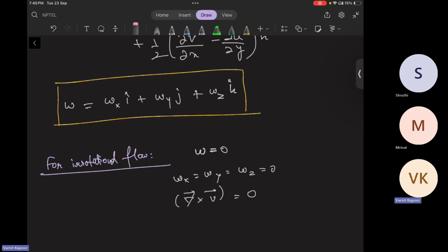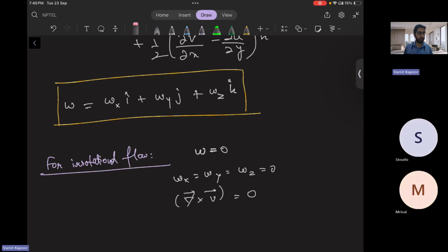All right. So let's come to the concept of circulation. Circulation is defined for the rotationality of the whole loop, not for an individual particle, because we are dealing with a continuum scenario. So I'm talking about the rotationality of the whole loop. It is nothing but a line integration of a tangential component of the velocity along the closed loop. It is a scalar quantity and it is independent of the slope of the loop and only depends on the area. You will get to know when we derive. And as we said, anti-clockwise is considered to be positive.